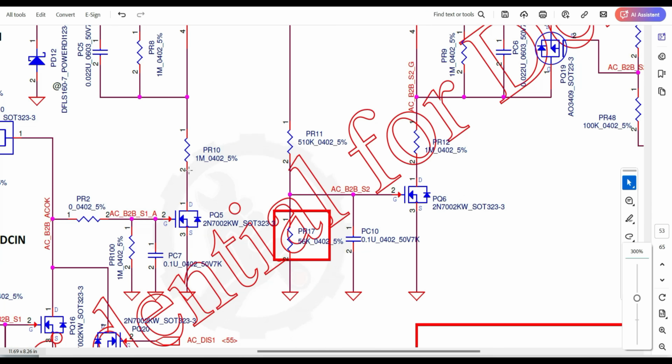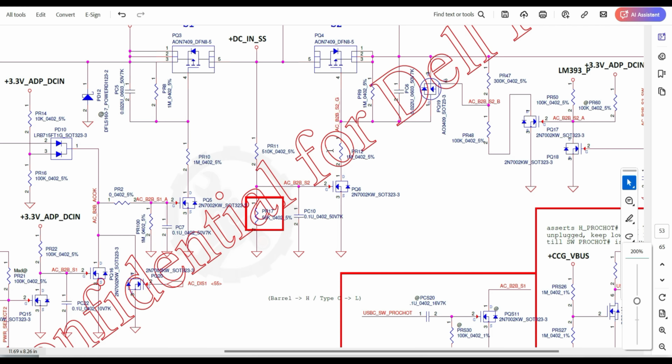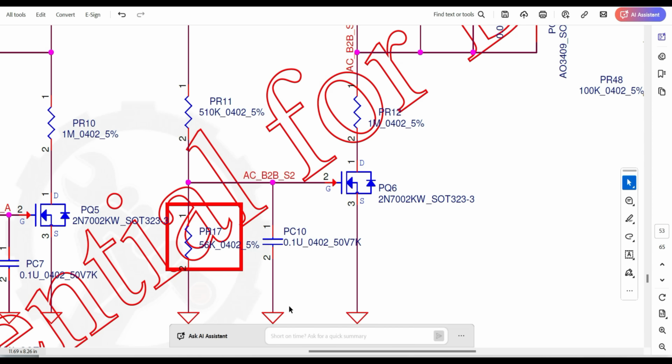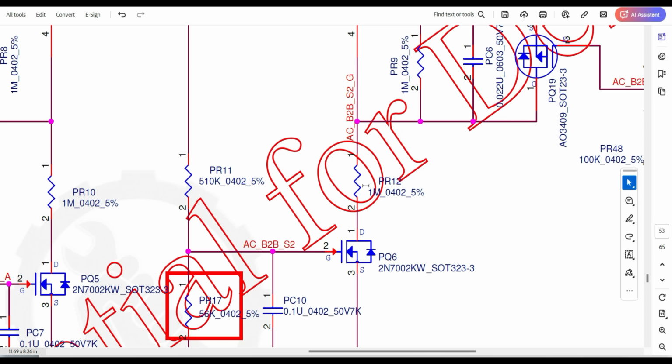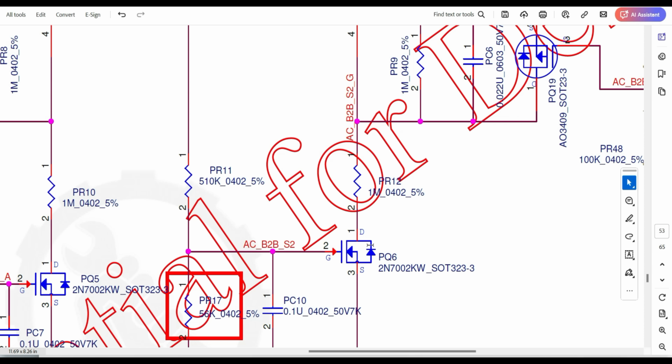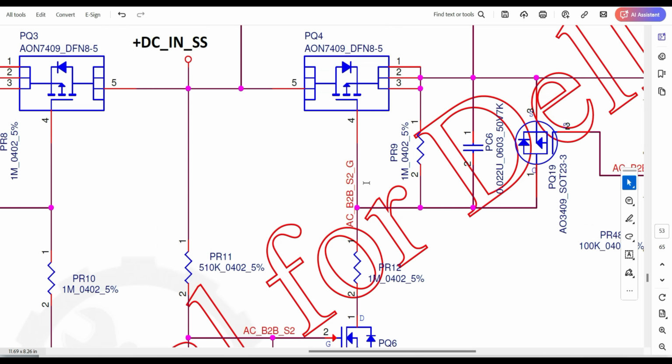This one I'll explain to you. How to read it? Here there are two resistors, one here and the other here. In case this component is active, it will connect 1 and 3, and then this path is called ground. Correct. If we consider this R2 and this R1, then we get a voltage divider. In case this component is in the off condition, the destination is not connected to the ground, then we won't consider it a voltage divider.